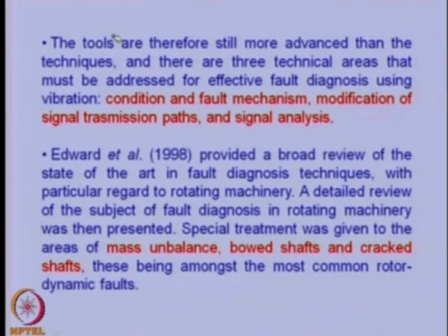So, the tools are therefore still more advanced than the techniques, and there are three technical areas that must be addressed for effective fault diagnosis using vibrations, that is condition and fault mechanism, modification of signal transmission path, and signal analysis.